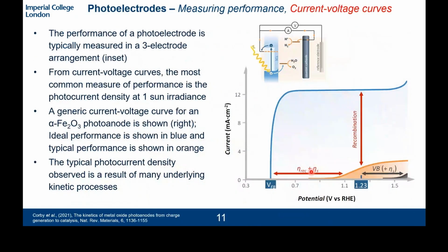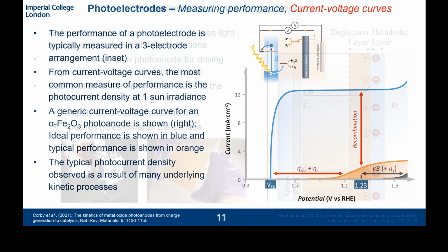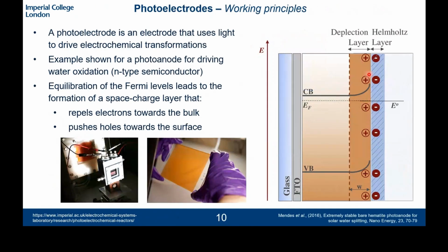And we can essentially break it down into 2 different processes. One is the recombination. How would you overcome recombination? By using a voltage to bend the bands sufficiently so that we can avoid electron and hole recombination by spatially separating them. So what you can imagine here is that if light comes in and is absorbed here, and we get an excitation of an electron from here to here, this electron will slide down this slide and go wee all the way over here, and this hole will go up the slide because electrons up here will fall into the hole, moving the hole upwards. So we get this really good separation of electrons and holes within the space charge layer.